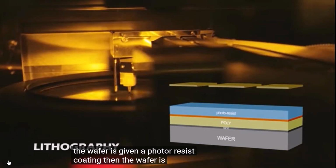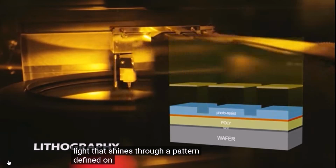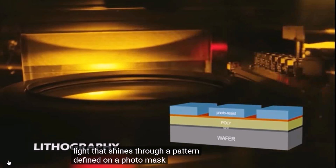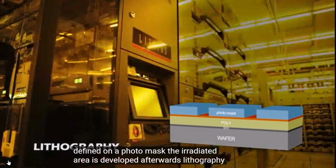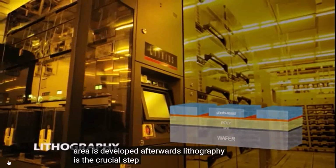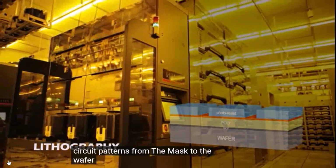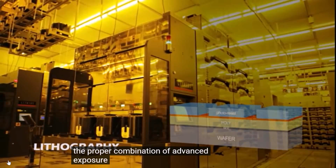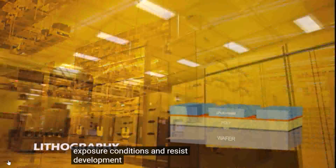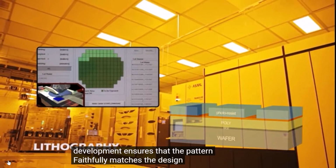Then, the wafer is exposed to UV light that shines through a pattern defined on a photo mask. The irradiated area is developed afterwards. Lithography is the crucial step that transfers all circuit patterns from the mask to the wafer. The proper combination of advanced exposure conditions and resist development ensures that the pattern faithfully matches the design requirements.